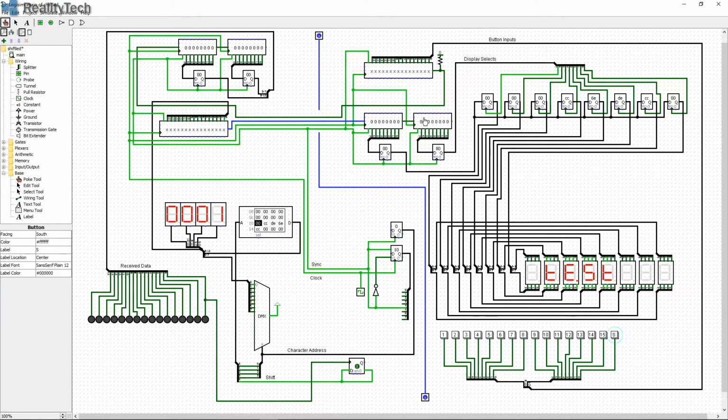So we're into the serial parallel converters, we shift them out, we lock them into the latches, we use the sync pulse to latch the data in, and then you can see what's going on here. If you look at these numbers, they will match where we're reading, what's currently in the EEPROM address that we're reading, and this represents the select. So here's your selects going in, here's your selects going out.